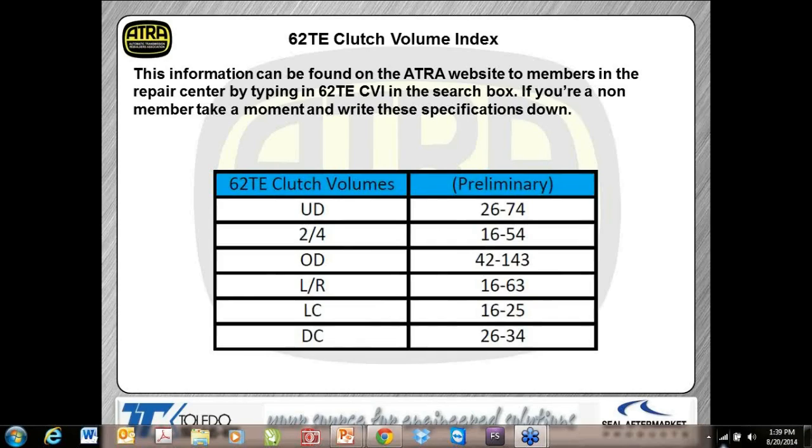Now, when we take the low clutch assembly apart, again, I'm showing the OE tool here to compress the spring. You can use whatever you have in the shop that works fine for you. The clutches in this drum are normal clutches, double-sided clutches. And you have the Miller tool number if you do want to purchase that tool.